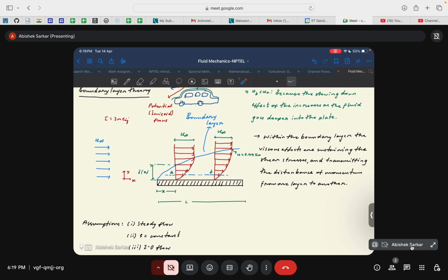As the flow develops along the length of the plate, the momentum transfer from the plate to the fluid is felt more. So if the boundary layer had grown something like this, then our velocity profile will be something like this. It has to be a bit less in this region, so that as it grows, it attains u infinity at a greater height compared to the velocity profiles at points A and B, and then again obtains the potential flow region. So velocity at this point would again be lesser than at point B.